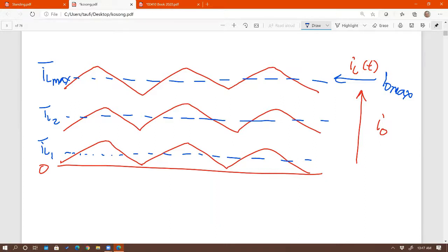Can you state the first part of your statement? My question is, in the equation V in times IL min average, you said that's equal to V out average times I out max average. So wouldn't that mean that at I out max, you reach IL min? Hang on. First of all, this equation should, in general, be this.